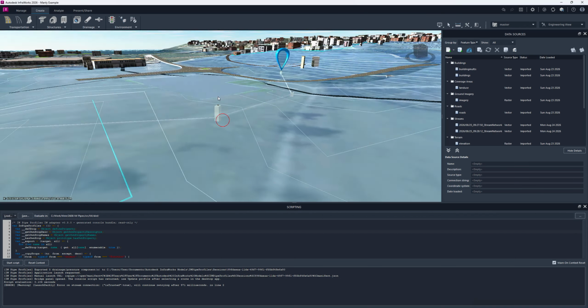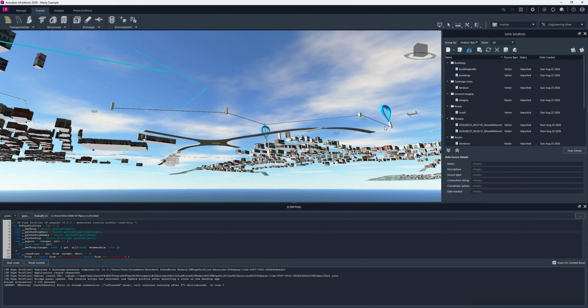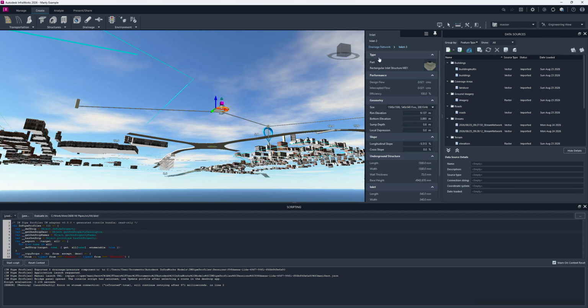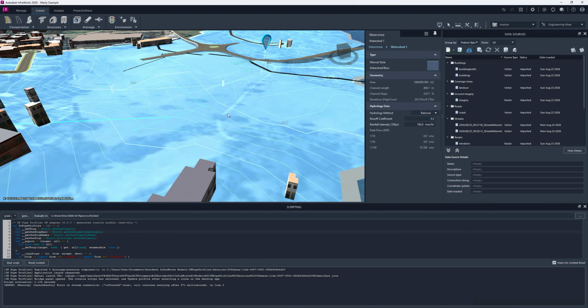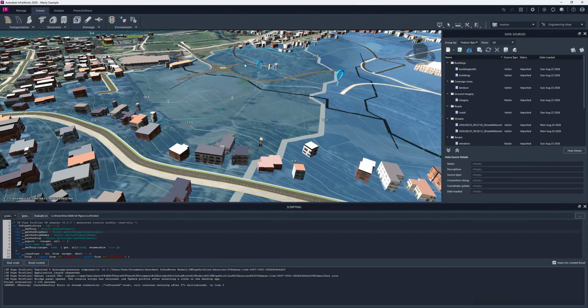Let me explain. What we have here is a very small line or system network with a couple of pipes, a couple of branches merging into a main branch. But if you select the elements, you'll see it's a drainage network part. This one is an inlet, it's a manhole. But you can see it's got a bit more hydraulic information. It's got the catchment, tributary area, time of concentration and runoff coefficient and so on assigned to it. So that's information that comes from the catchment. Again, if I select the catchment, you'll see it's got its own properties that are automatically calculated.